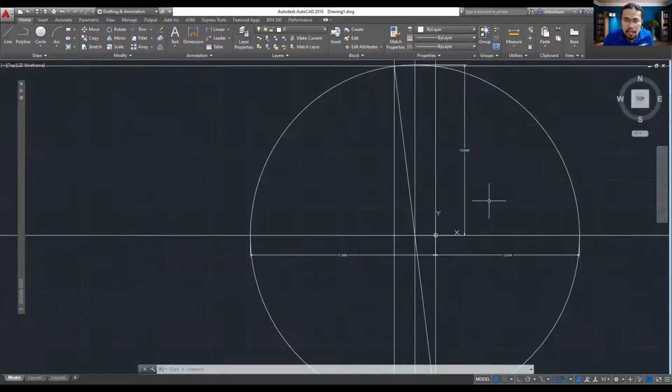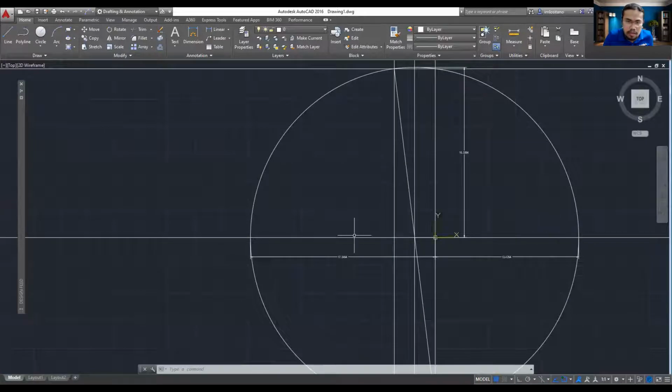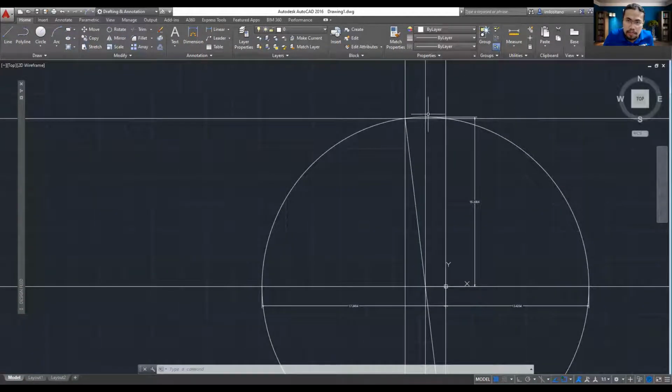Take note that for the principal stresses, since they are along the x-axis, the accompanying shear stresses are 0, while for the maximum shear stress, the accompanying normal stress within that orientation in the body is the average of the principal stresses.